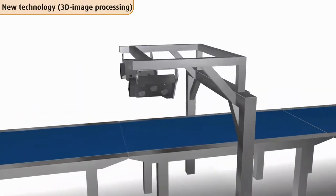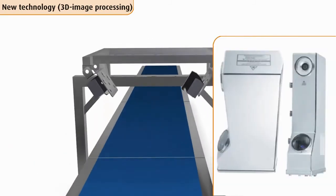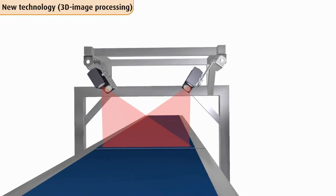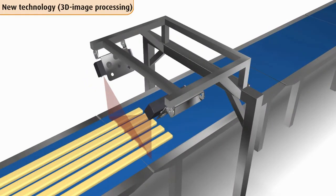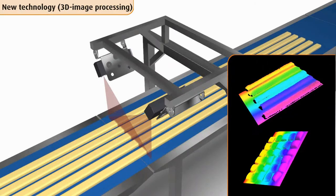The newly developed image processing system functions in the following way. Two cameras are fastened to a special construction above the dough strand line. They scan the complete width of the strand from above and generate a laser beam which can be seen as a light barrier above the conveyor belt. Whilst the dough strands are being transported through the laser beam, the smart cameras record the three-dimensional form of the strands. Even the slightest irregularities in the surface are detected, converted into data and processed by the computer unit.